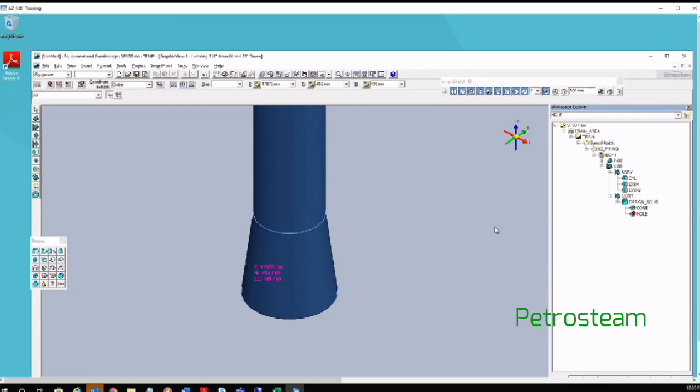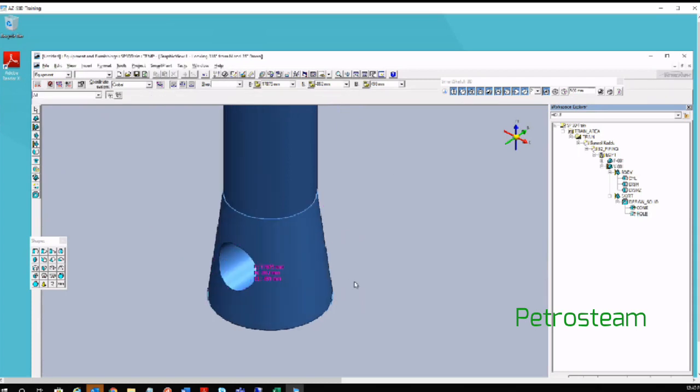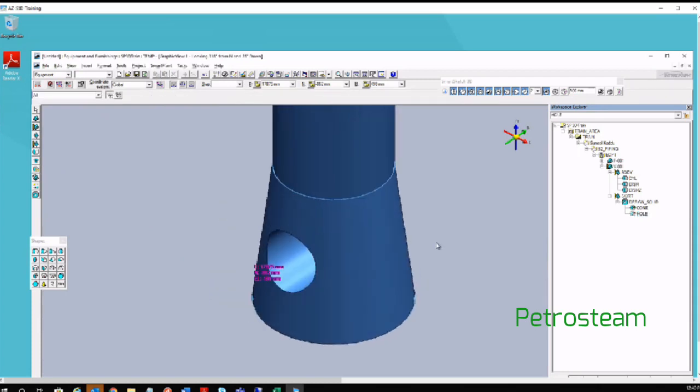Once they confirm whether they need a hole or not, if they don't need it, you can delete it, or if they need it, you can change it back to negative shape or subtract shape. So this is how the third property, suppress shape, will work. Although the cylinder is there, it does not have a positive or negative impact on the shapes. It will ignore the shape.